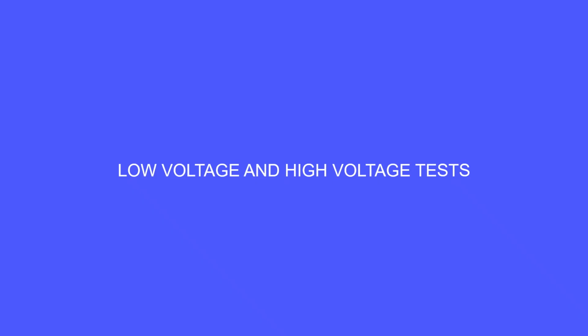We will be discussing static testing, which is when the motor is not operating, disconnected from the power source and locked out. It is important that anyone performing testing of motors understands and follows the lockout-tagout requirement of their facility as well as NFPA 70E safety guidelines.